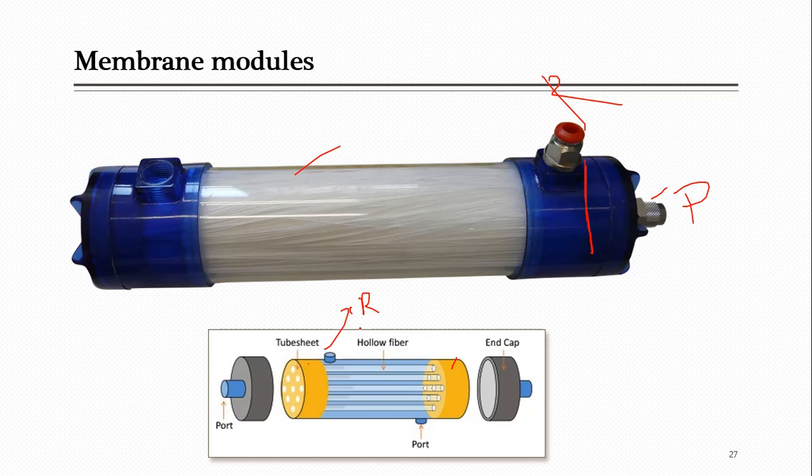So there are various structures in which they can be arranged or placed. Like here you have two openings on the shell side, and I should say, just to give it similarity to shell and tube, there is a shell side with two openings and a tube side, but on the shell side there are two, and on the tube side there is only one. By the way, you will be thinking, on the other end are the tubes open? No, they will be clamped on one end.